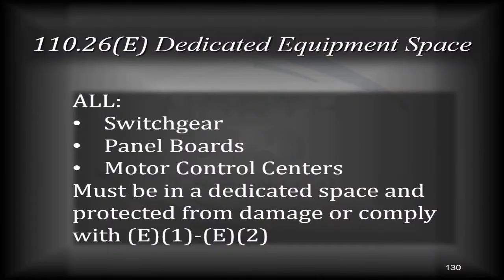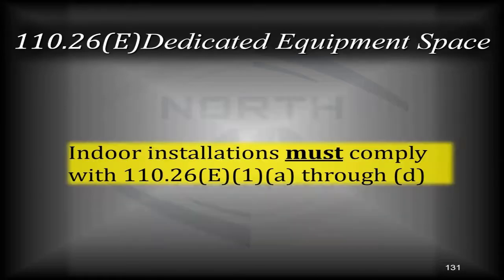110.26e talks about dedicated equipment space. All switchgear, panelboards, and motor control centers have to be in a dedicated space and protected from damage or comply with E1 through E2. Well, indoor installations also must comply with 110.26 E1a through d.